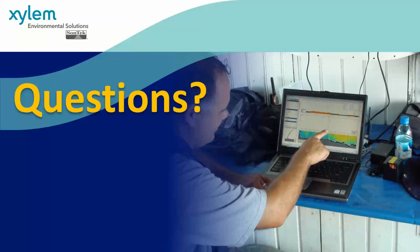And if it seems like everything that Xue just mentioned is okay and you're still getting a restricted range, then I'd recommend you call or email tech support to help you walk through isolating whether it's the hardware or something else. Another typical source of interference that we don't always think about is that we humans are made up of a lot of water. So if you're standing between your PC and the radio antenna and the ADCP, you could be blocking the signal as well.